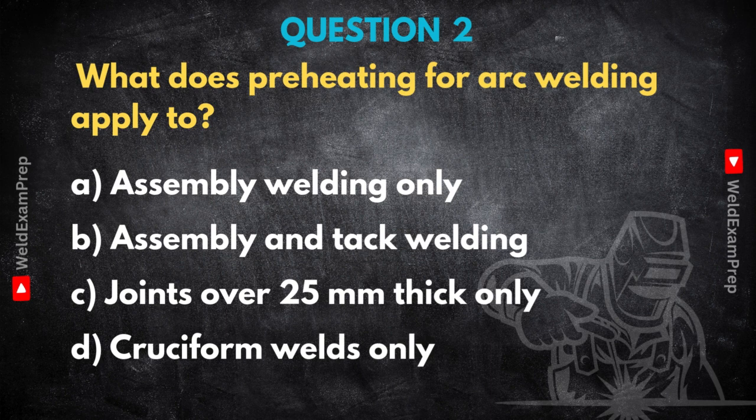It gives hydrogen more time to diffuse out, which drastically cuts the risk of hydrogen cracking. It also helps reduce residual stresses left over from welding and minimizes distortion. So multiple benefits. Okay, but the question is what it applies to. Assembly welding seems obvious. It is.